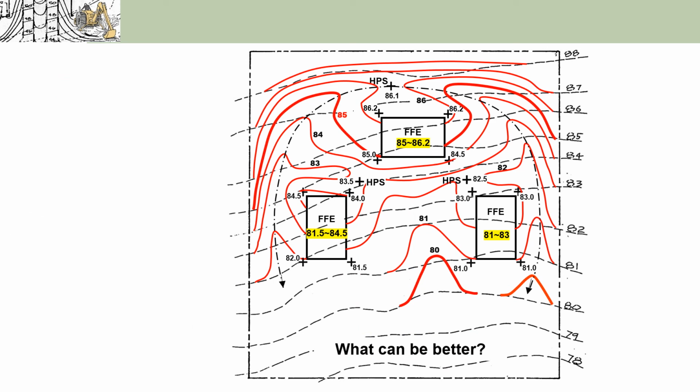So now we have completed our draft. It is time to critique it. Okay, the red contour lines here actually made it quite clear what are some of the areas of improvement. There are so many contours that have been moved far away from their original locations, which means there is a lot of earth moving here. We're causing a big site disturbance with this draft. So can we make it better? And how do we make it better?